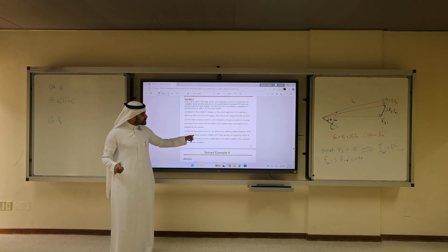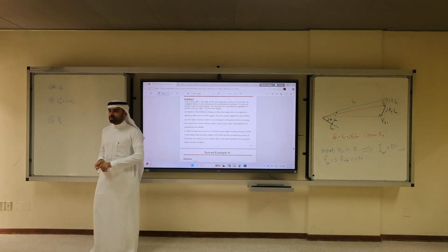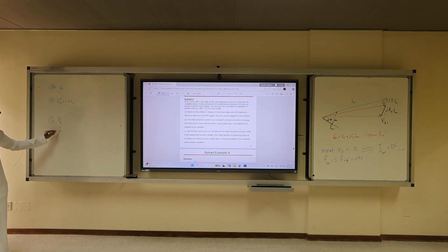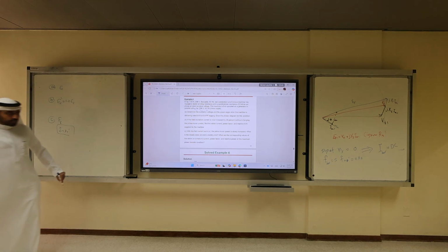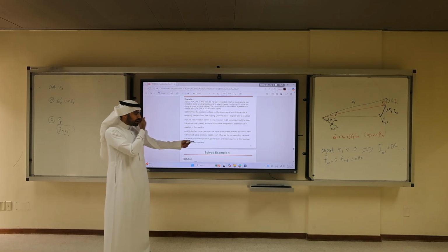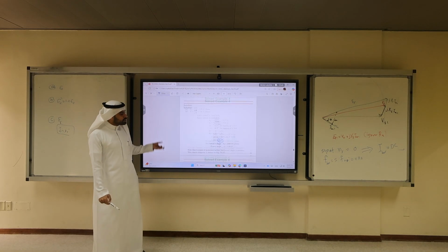What is the steady state stability limit? You remember stability limit? It gives me one piece of information: delta is 90 degrees. What are the corresponding values of the armature current, power factor, and reactive power at this maximum power condition?